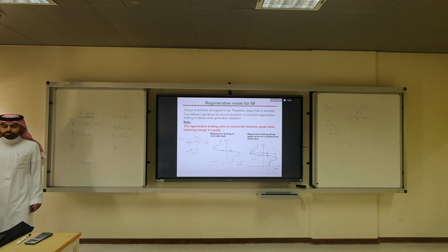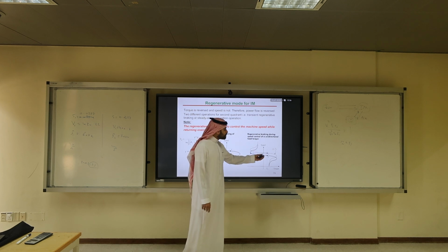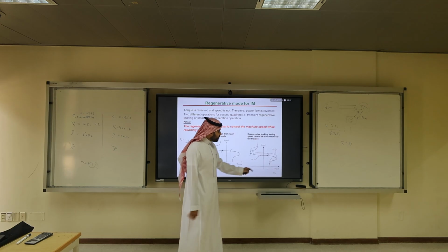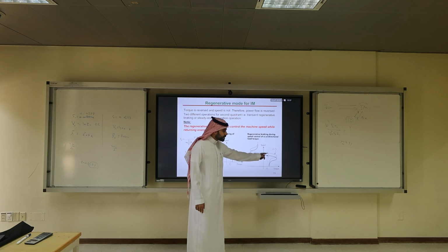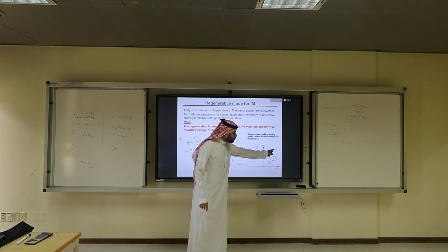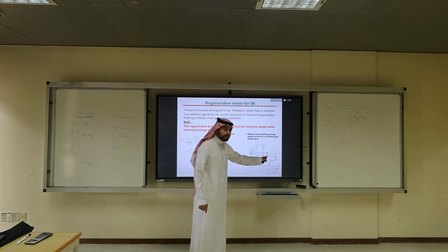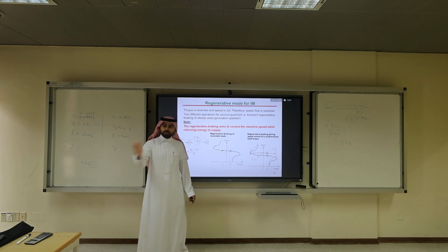Okay? So when you apply, for example, an elevator unidirectional, you apply speed control. You want, for example, to reduce the speed of the elevator a little bit. You go from F1 to V1, you apply V over F, you apply on this curve V3 and frequency 3. But can you jump in the speed directly? Or we have to go gradual?